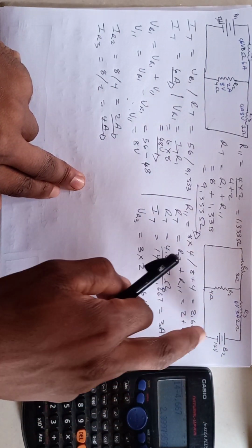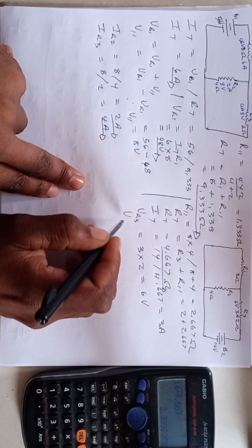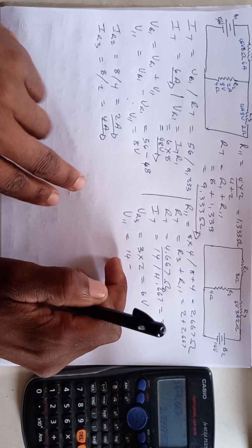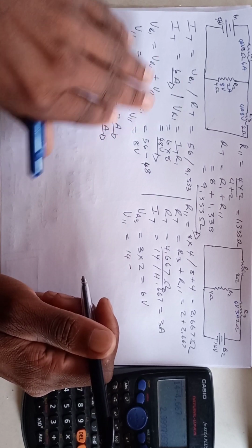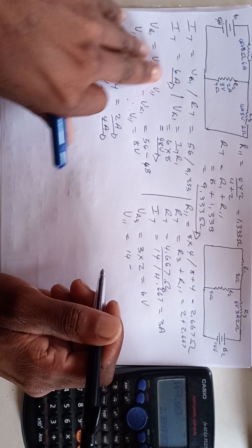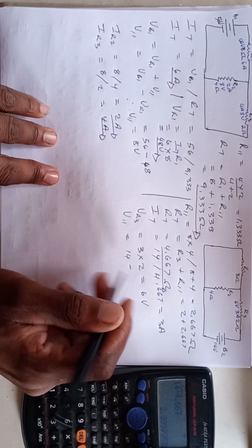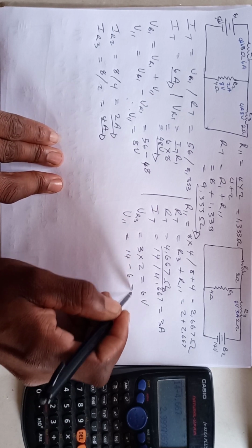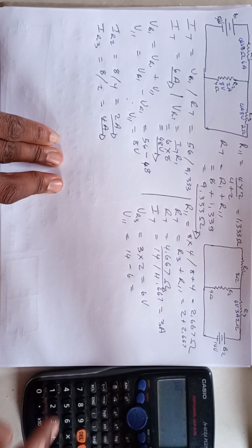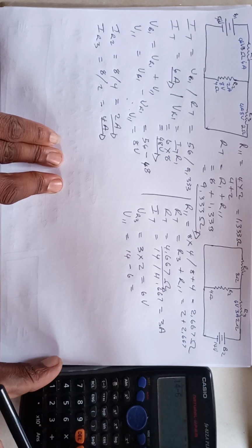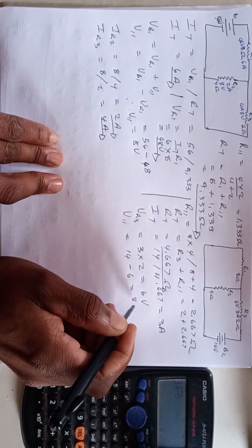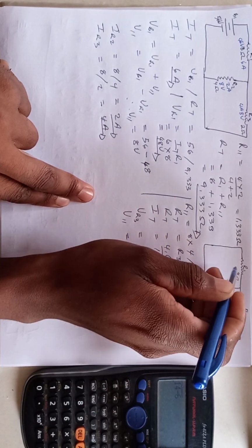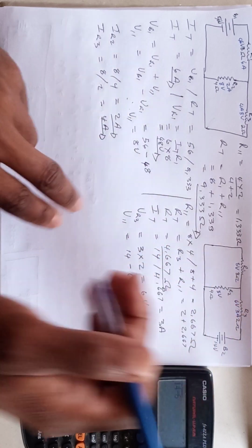We can use this voltage and this voltage to calculate the volt drop across the parallel circuit, which is going to be 14 minus, I'm deriving formulas the same way that I did on this side. So if you lost here, just come back on this side. So it's going to be 14 minus 6. We get 8. So the voltage across the parallel circuit is 8. So we know that the voltage here is 8 volts and also 8 volts there.